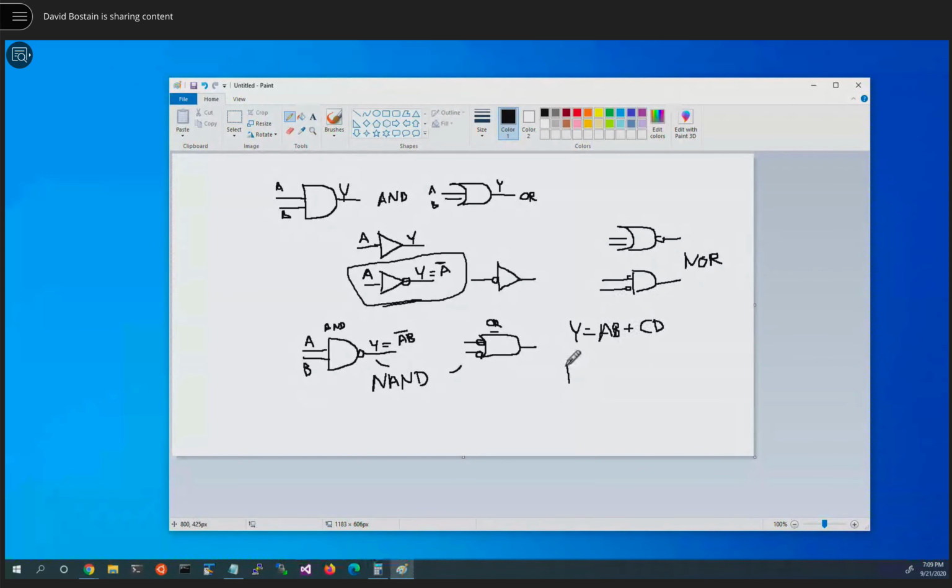So we could envision writing two AND gates, one OR gate, taking these as inputs to the OR gate, taking our final Y right there, and then our inputs coming in would be A, B, C, and D. So if we had a circuit which could do the AND function, and we had a circuit, this is a terrible looking OR, but if we had an OR function, the result here would match the truth table for whichever truth table this happens to be the equation for.